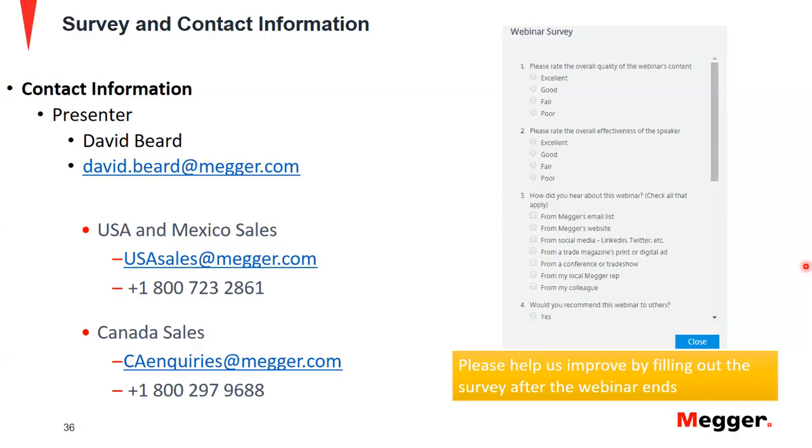Once you get that run, it will give you an option at the top by the report that says add to report. If you're in the timing screen or one of our predefined screens, like a transformer differential screen or a state sequencer, then those automatically populate that test into a test file. And as you were looking, I was going into the T with the lightning bolt, which would give me my different tests and allow me to group those tests how I see fit.